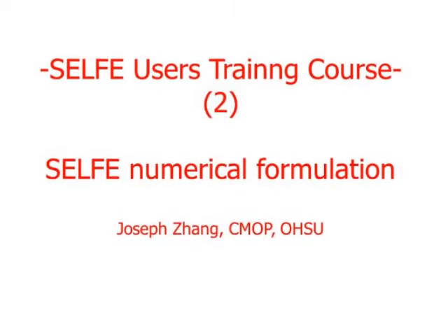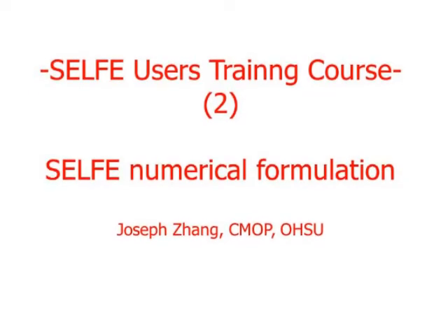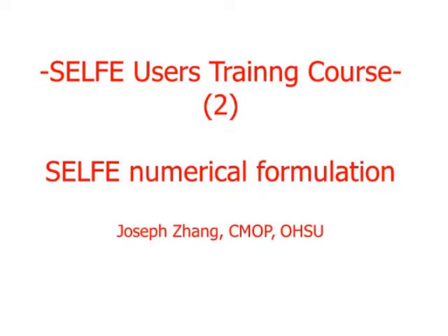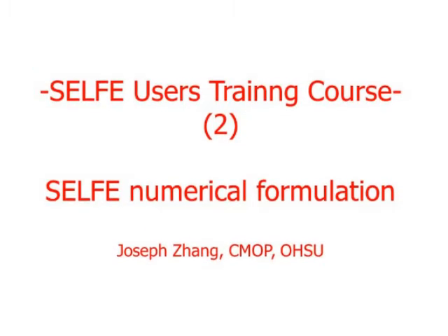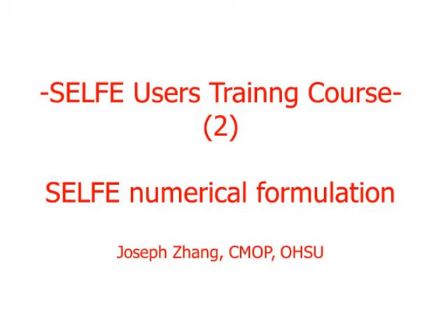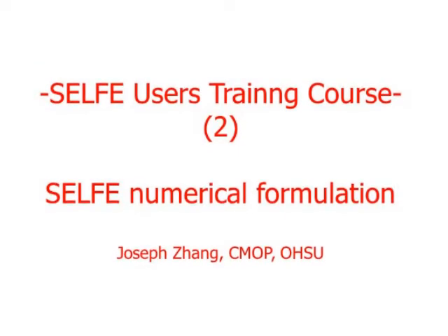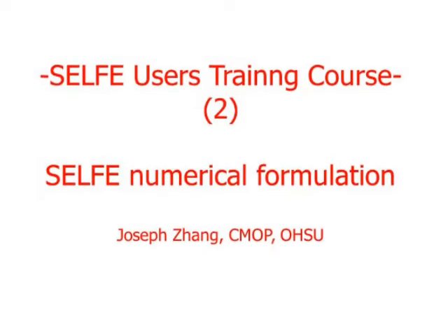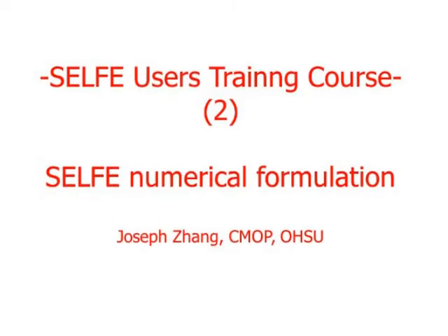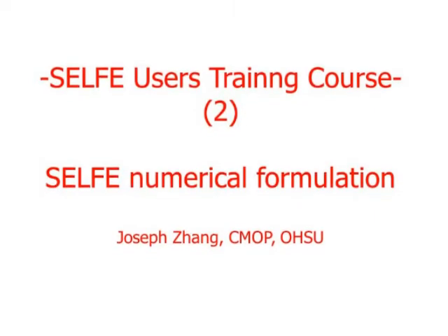But the most important thing here, as far as the transport equation, is the advection term, how you treat the advection term. Okay, so here on the left, the second term on the left-hand side, you can see the summation of advective fluxes across 5 faces of the prism. Okay, Tj star is still undefined. Okay, we need to find a way to evaluate Tj star. So we threw out all the irrelevant terms, all the easy terms. We just concentrate on the advection.